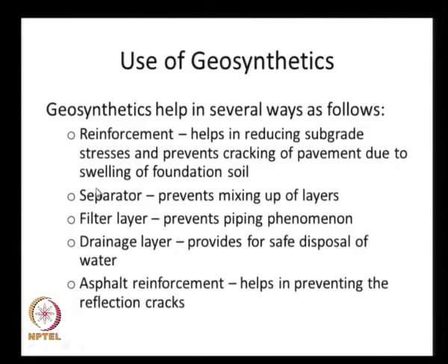And we can use a geosynthetic as a separator that prevents intermixing of the materials in different layers, as a filter layer to prevent the piping phenomenon, as a drainage layer to provide for safe disposal of water whatever enters our pavement, and as an asphalt reinforcement layer or a paver reinforcement layer. It helps in preventing reflection cracks.